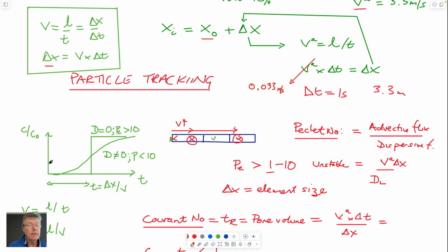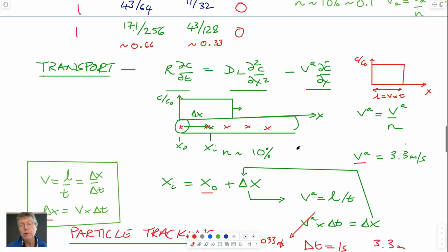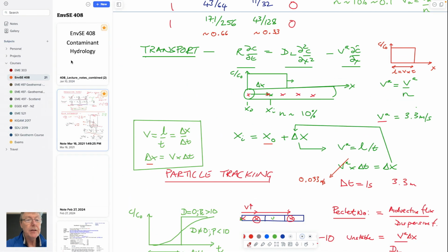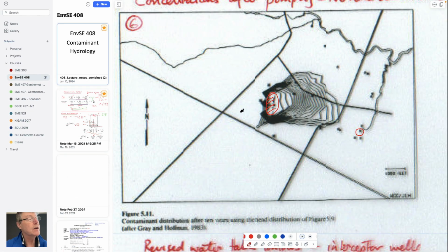That would allow us to calculate the observation at the compliance location in terms of the residence time distribution. But I guess more importantly, we might be interested to see exactly what the plume looks like in plan view, exactly what the concentrations would be as you go downstream. So just like Borden, these would be almost zero concentration. The biggest concentration would be closest to the source, and we have a full distribution of those as we get downstream. We're looking at flow only with a velocity in the direction perpendicular to the equipotentials, but what will also happen is you get dispersion that occurs laterally as well as longitudinally. And so we know what these plumes would look like as you go downstream. So it merely allows us to do that.